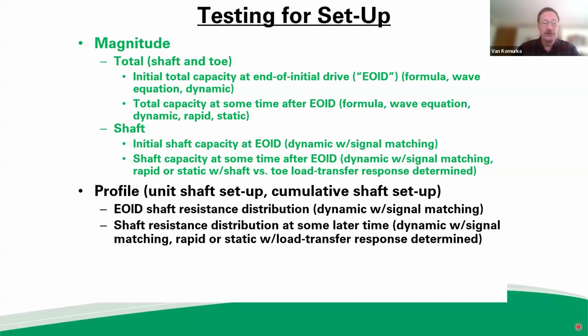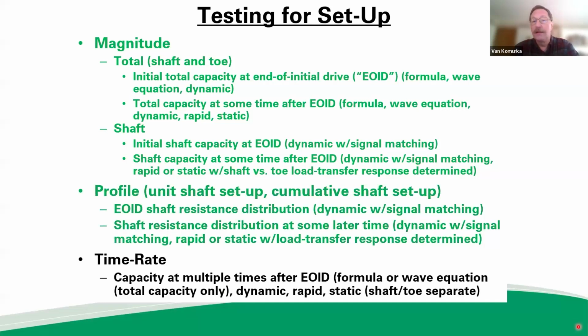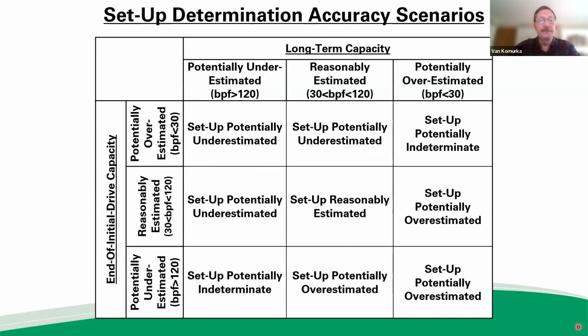It's just as easy to do. And if you want time rate of setup, then you need capacity at multiple times after end of driving. And we'll look at time rate and how setup responds to time rate as well. So again, you need the total capacity during end of drive, and then at multiple restrike times after driving, and that will give you a time rate response or relationship.